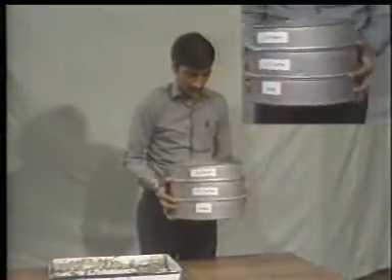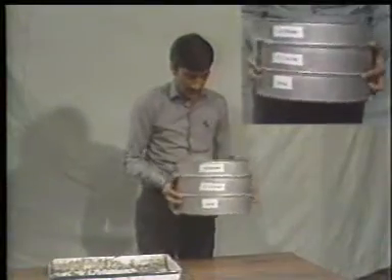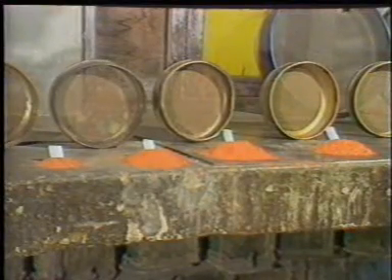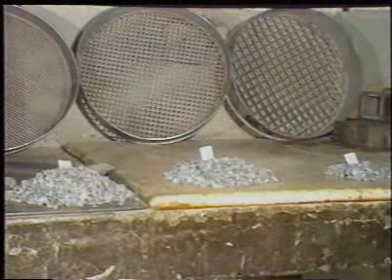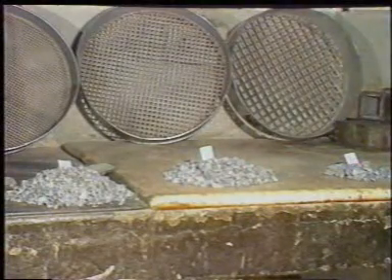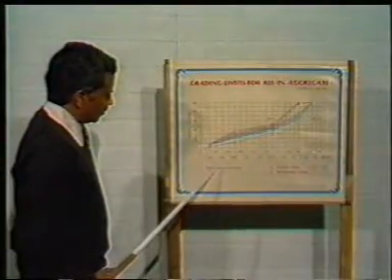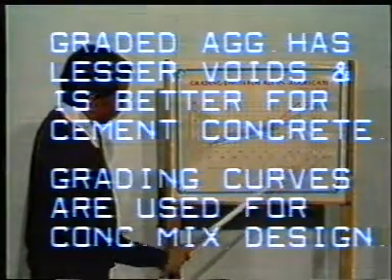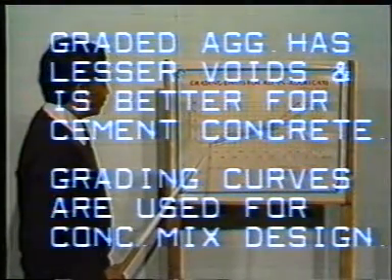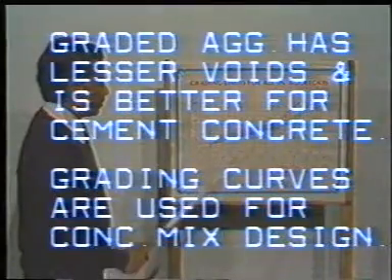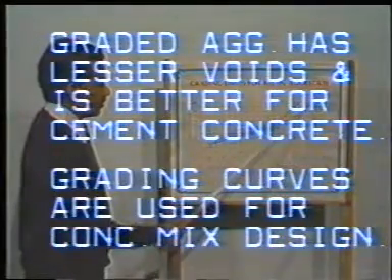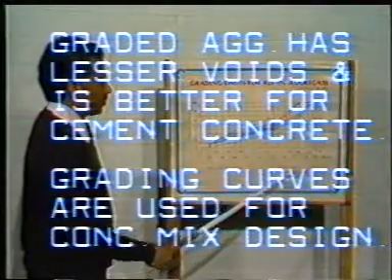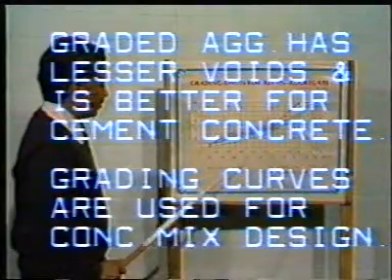Grading of aggregate plays an important role in mix design. It can be determined by sieve analysis. Graded aggregate has lesser voids and is better for cement concrete. Grading curves are used for proper grading of aggregates for the concrete mix design.